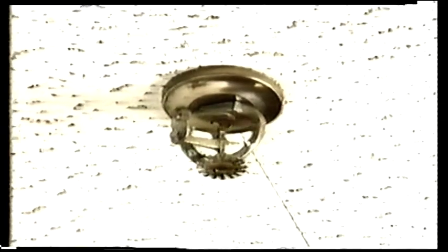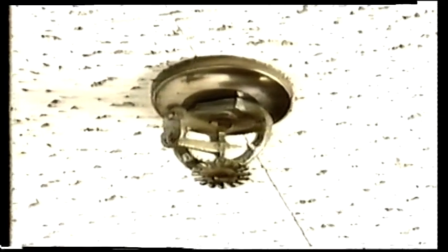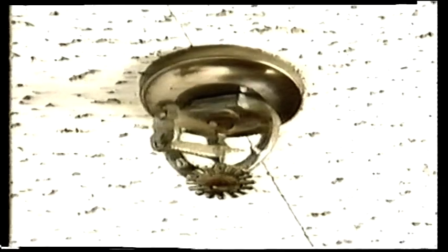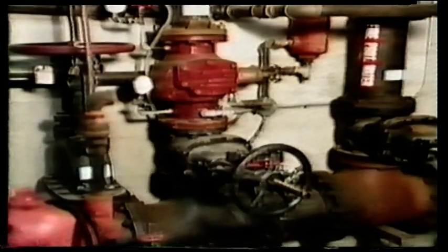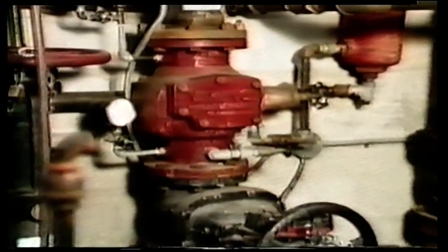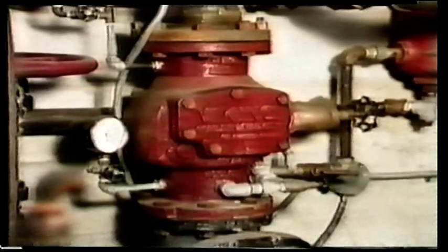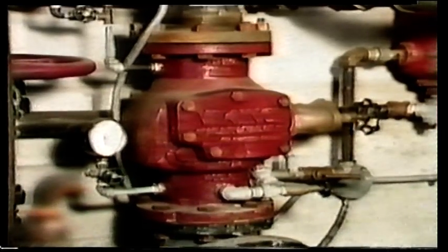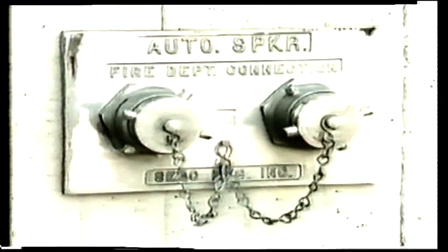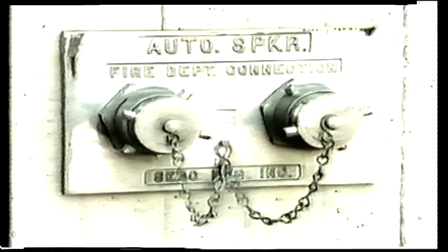Next, the fire protection system is examined to see if any cross-connection protection is afforded other than the alarm check. The survey team must remember that fire protection systems may contain black or stagnant water on the downstream side of the alarm check. Chemical additives may also be used in fire protection systems. The survey team must also be concerned with the presence of Siamese, or fire hose connections, which are usually located at street level, protruding through an exterior wall of the building.